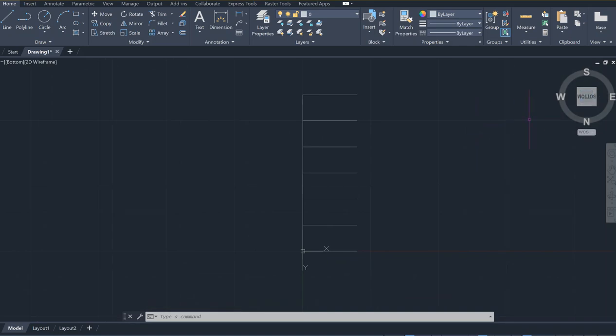And right now I change my view to the bottom view, okay? And why is it doing that? So that I can have the XY plane in front of me. Okay, I want to have the XY plane in front of me. Why do I do this? Regular lines are created on the XY plane, okay, unless you are designing 3D polylines and so on.